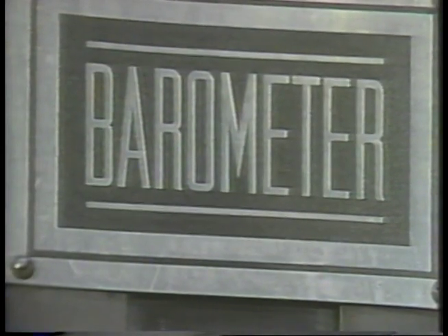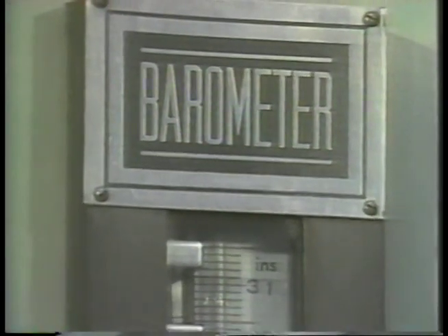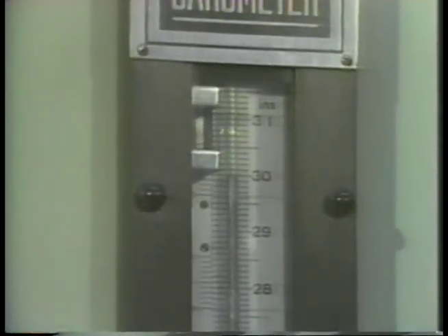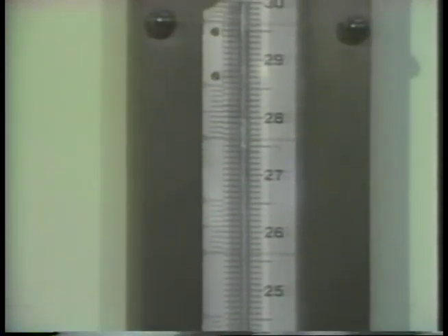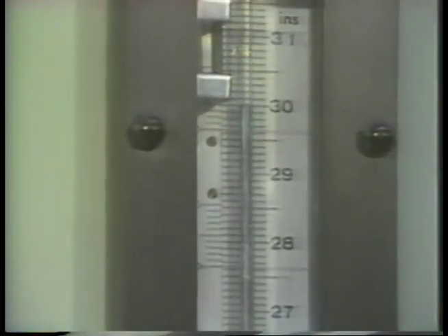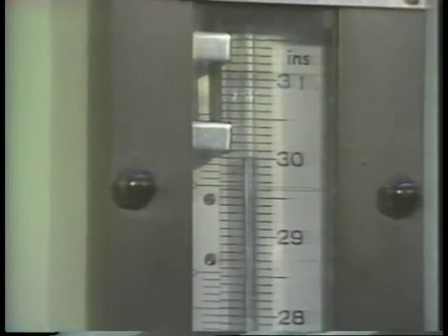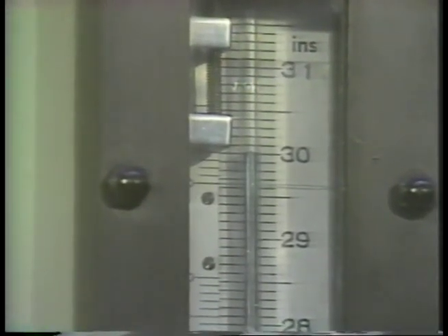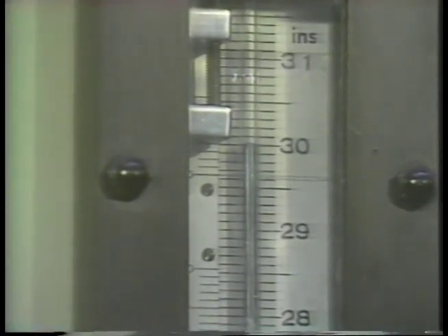Now, today, barometers are constructed in much the same way. A tube is filled with mercury and placed in a container of mercury. The height of the mercury column reflects the atmospheric pressure. A scale alongside the mercury column allows the mercury column to be read in inches of mercury. As atmospheric pressure changes, so does the height of the mercury in the tube. If atmospheric pressure increases, the height of mercury increases. And if atmospheric pressure decreases, the height of the mercury decreases. At a typical 14.7 psi atmospheric pressure, the barometer will read 30 inches of mercury.